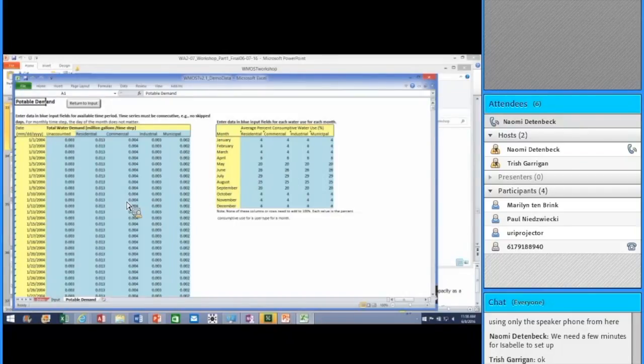The initial setup will reserve some space for unaccounted for water that's always present, but in setting up the WMOST, you would specify how many users you want to have. In this case, we had in the blank WMOST specified 4 users, and then in the blue space at the top, you would type in the labels you want to provide to these users, and those labels are carried forward in all of the tabs that deal with demand. For each of these users, you will then need to provide a time series of the demand.